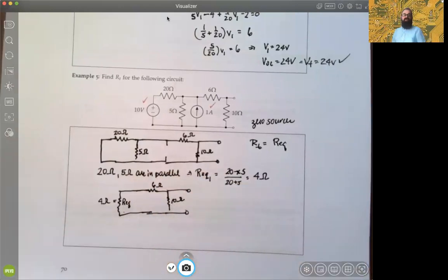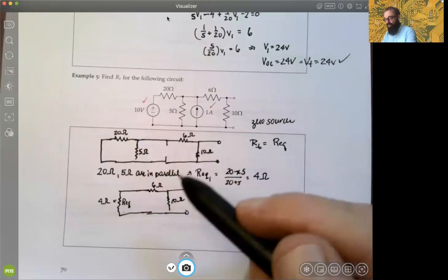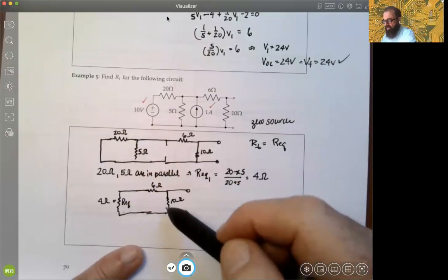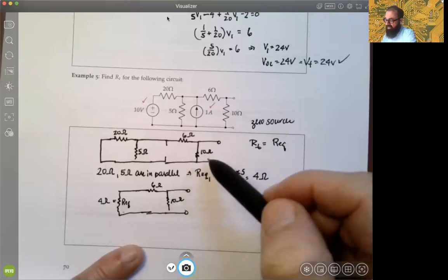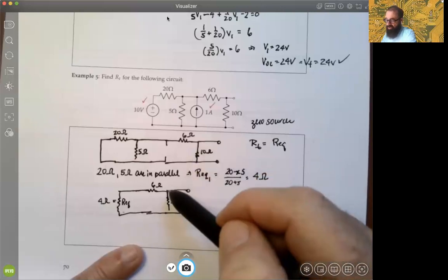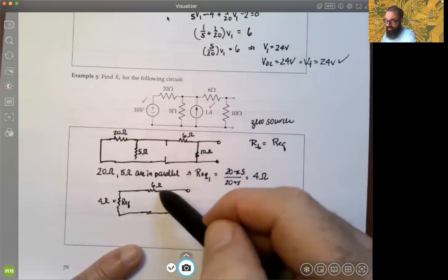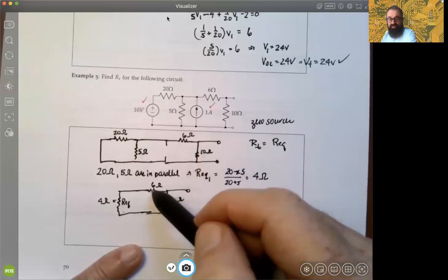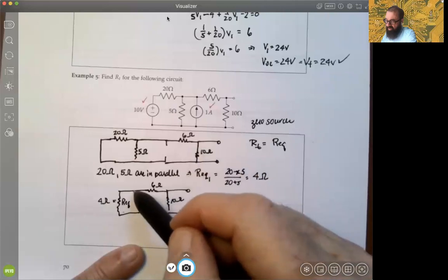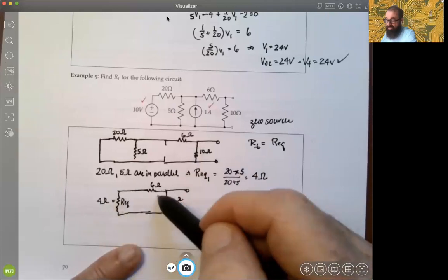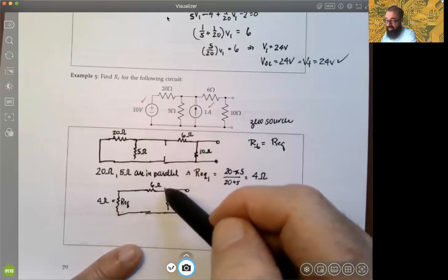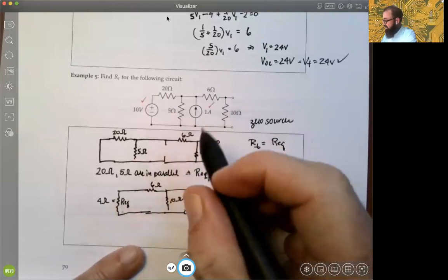But notice it's important here that we draw these correctly, because you can see from right to left, you have a juncture here of leaving either through 6 and 10. But once you come through, if you were tracing through this resistance, 6 ohms here, and then you came into that one, I would hope you'd see immediately those two are definitely in series. They're end to end in this case, okay? They're not in parallel.